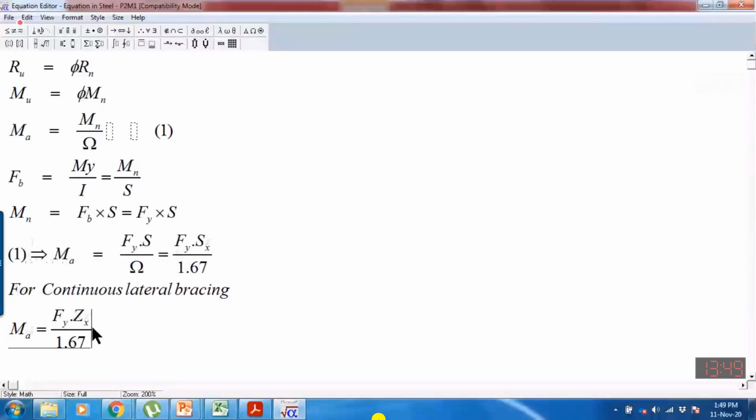This plastic section modulus I will explain when we start the beam topic, when we have the on-campus classes. But for the time being, you can assume that if a beam fails at a stress value more than Fy, then instead of using the elastic section modulus, we are supposed to use the Zx plastic section modulus. So the plastic section modulus is always more than Sx. But here we are assuming that in our case, this value is equal to this one.